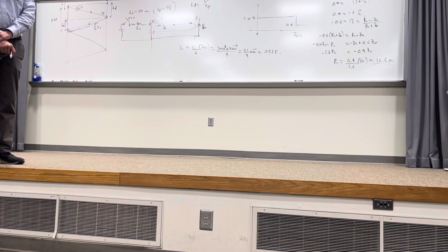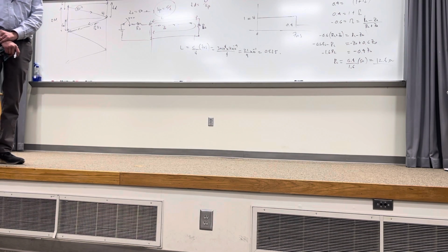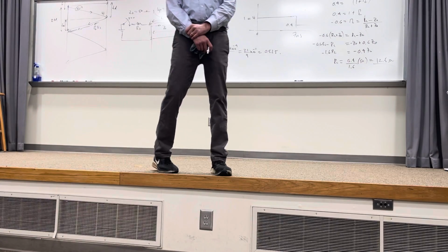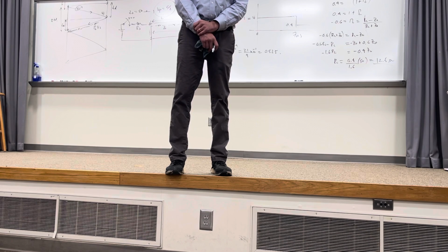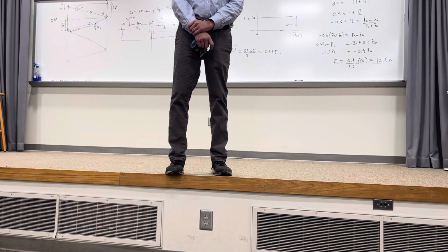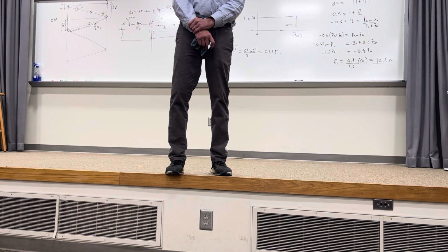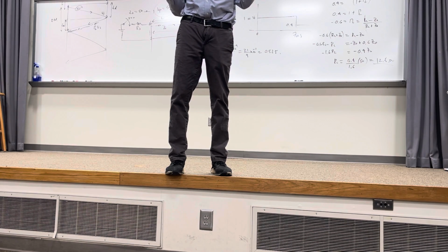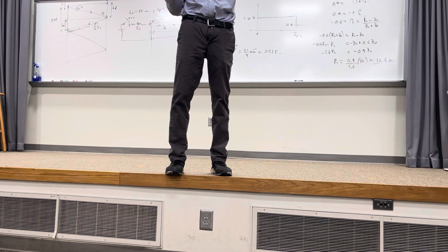Something? Yeah. So that was for a resistive load. In the book, he briefly mentions if you have a reactive load, it will... Yeah, I don't cover that here, and the thing about reactive loads is it's going to be a differential equation. Generally speaking, when you have an inductor and you strike it with an incoming wave, the impedance of an inductor looks infinite the instant the wave hits. It's like an open circuit.